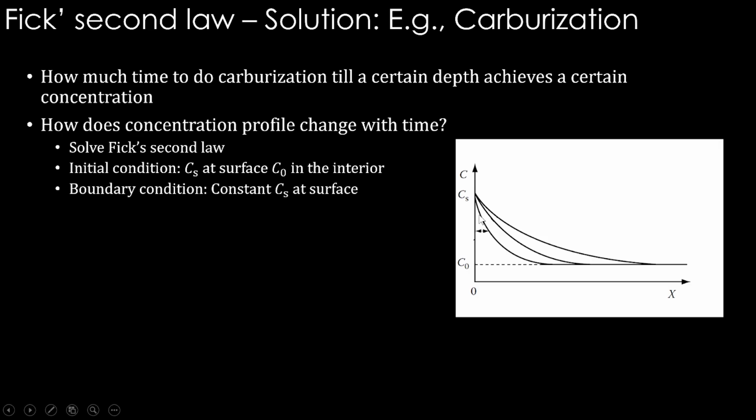Then we have to keep drawing these concentration profiles after different time intervals. There is a particular time interval after which, if you draw the curve, you will see that the location you are looking for would have achieved the desired concentration. So what we need to track is this concentration profile with respect to time. This is what we need to track.